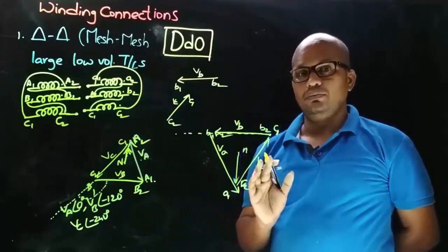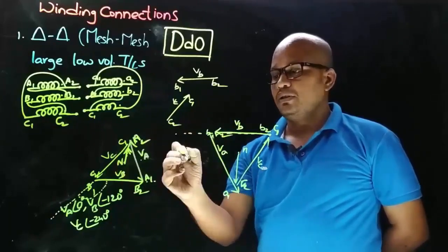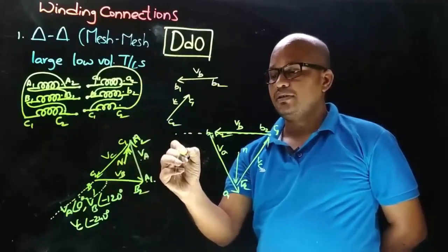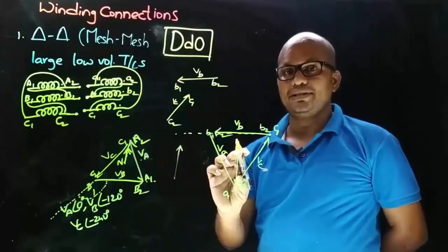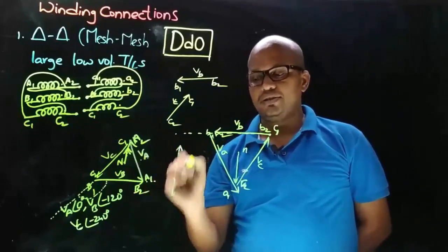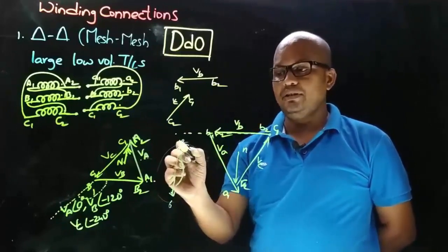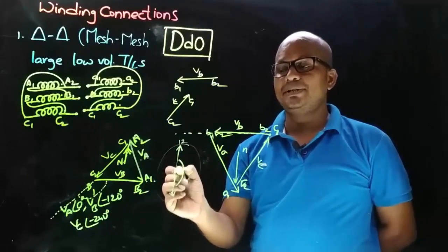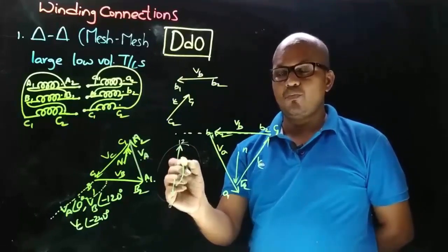Okay, and now just observe by superimposing this diagram on this diagram. Let's take this reference phasor as minutes needle, okay, means big needle, and this phasor for comparison, that is LV side. So if you superimpose this on this, the diagram will look like this. So in clock notation this will represent 6 o'clock, and the angle between minutes needle and hours needle represents the LV side voltage phase displacement with respect to HV side. So here the angular displacement is 180 degrees.